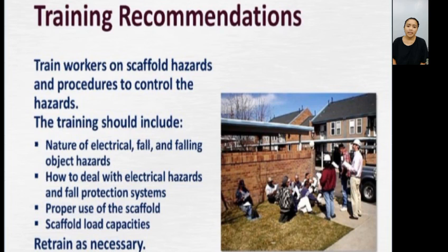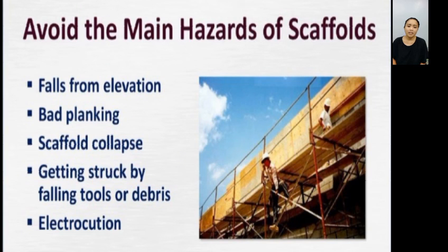Train workers involved in erecting, disassembling, moving, operating, repairing, maintaining, or inspecting a scaffold to recognize its hazards and the correct procedures to use. Avoid the main hazards of scaffolds: falls from elevation, bad planking, scaffold collapse, getting struck by falling tools or debris, electrocution.